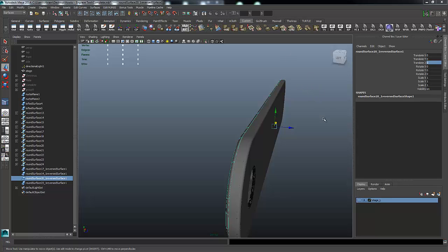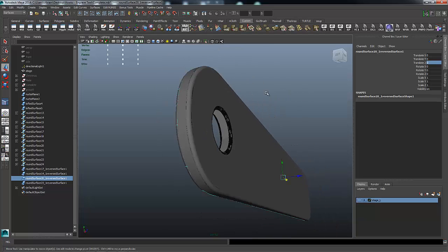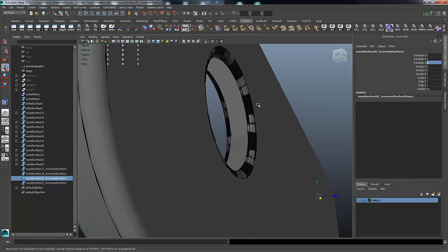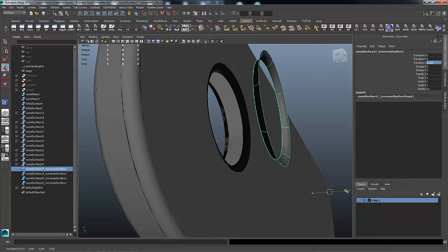Okay, I'm back. I accidentally stopped the video, so there'll be a part 2A and a part 2B, but I figured out what's causing this. I'm not quite sure what's causing it, but I know what the problem is. When I did this round, Maya's creating two surfaces. I have keep originals turned off, so I don't know why I'm getting that second surface.